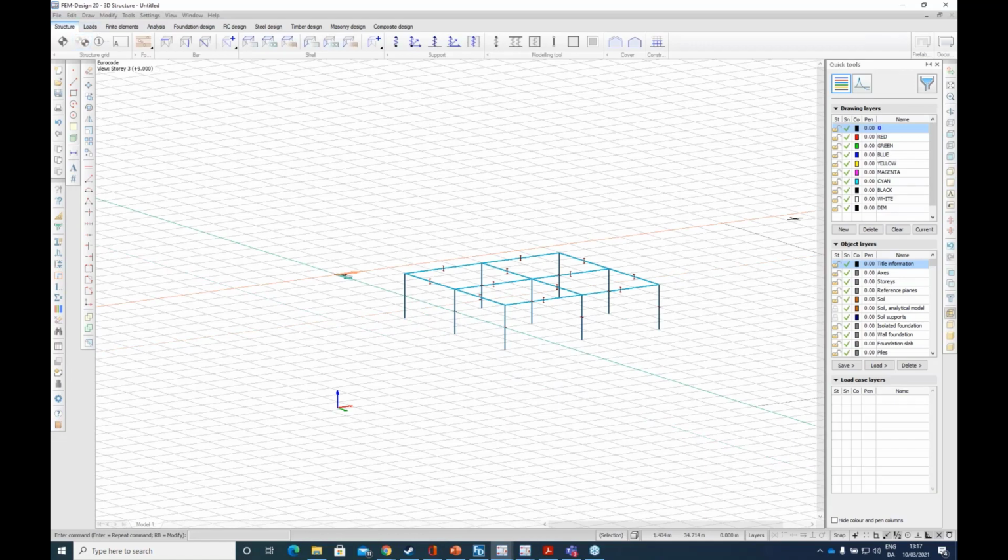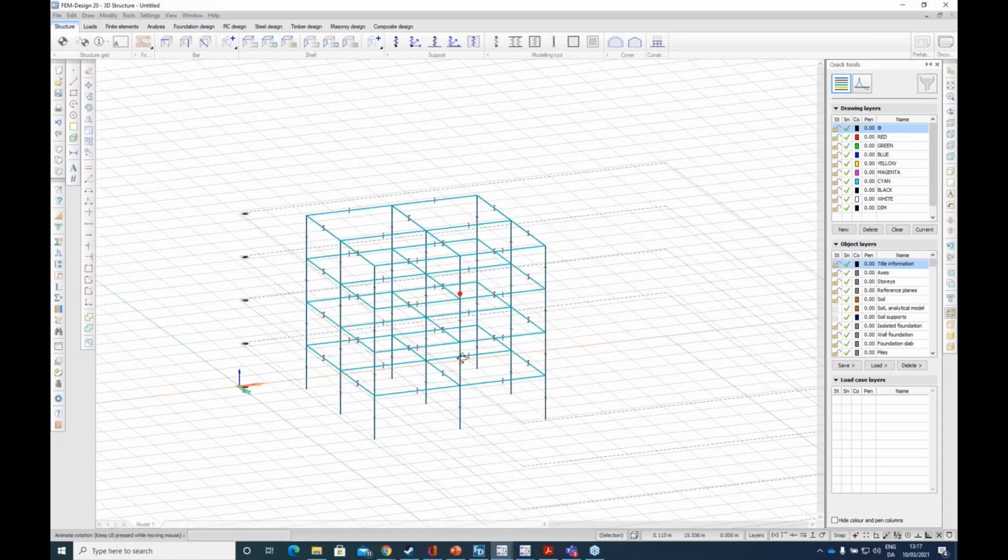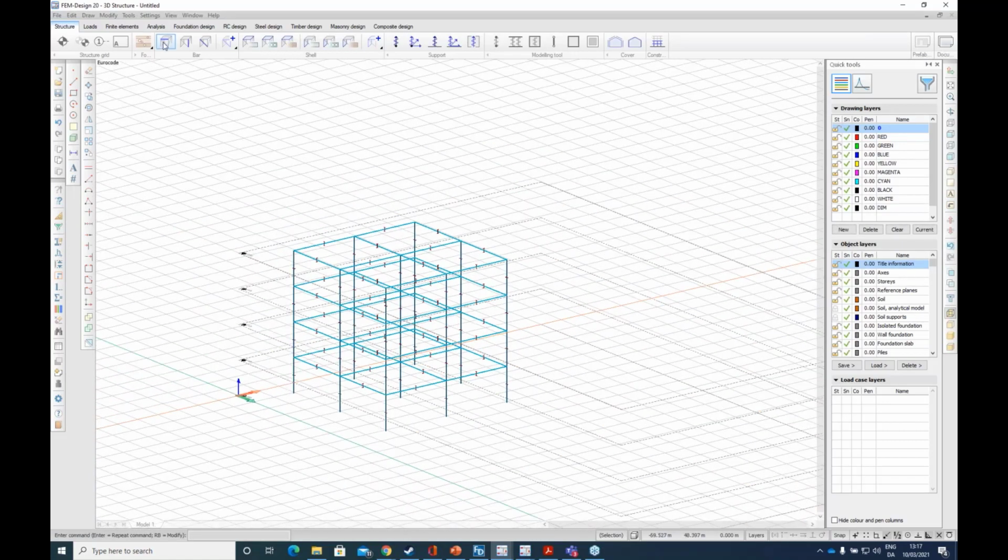So I can see that I can model my structure directly in my workspace by defining all of my structural elements: beams, columns, and under I have truss members here. I have plane plates, which are surface elements. I can define profile plates, timber plates, plane walls, and timber walls. You can define CLT elements as well. We'll take a look at that a little bit later.